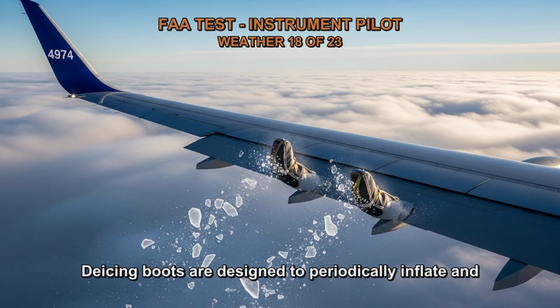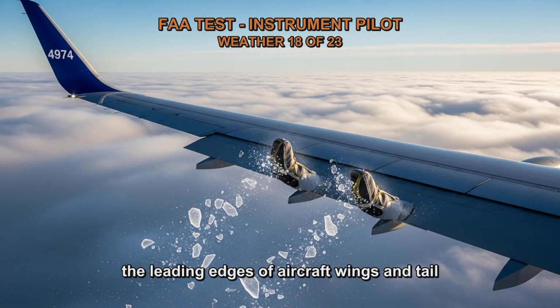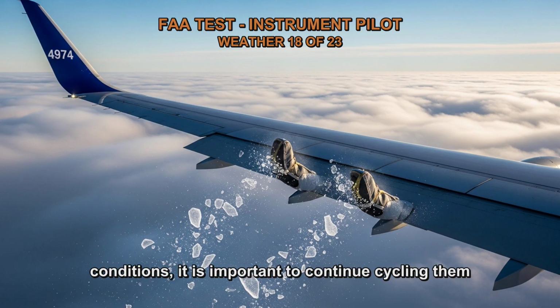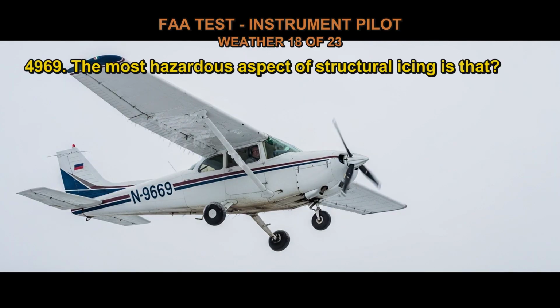De-icing boots are designed to periodically inflate and deflate to break and shed ice accumulation on the leading edges of aircraft wings and tail surfaces. While the boots are typically activated during icing conditions, it is important to continue cycling them after exiting those conditions.